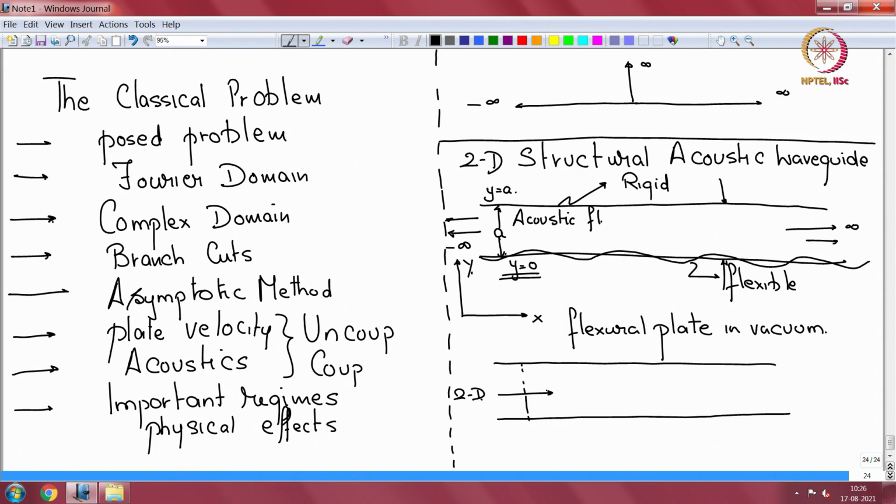You will have a plane wave propagating, then you will have the next cut-on wave propagating, which has 0 velocity at the walls, and then the next level wave cutting on, and so forth, and all higher orders which start with 0 velocity here will be propagating. These are higher order modes of a duct.